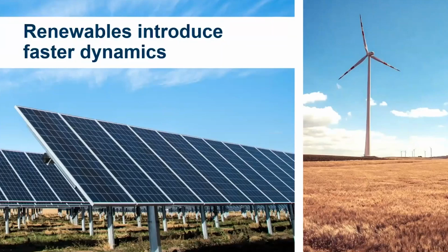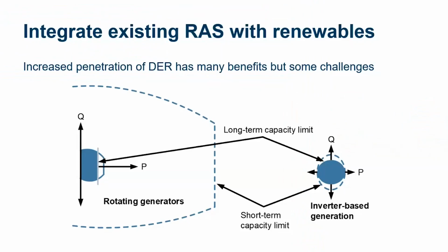These dynamic sources are continually being added to the power grid, adding opportunities to create more resilient operation of the power system. The inverter-based distributed energy resources, such as PVs and wind turbines, and energy storage systems have much different characteristics in comparison to traditional sources of generation. While they may lack the short-term capability of rotating generators, they can, in some instances, such as inverter-based energy storage systems, offer 4-quadrant control.